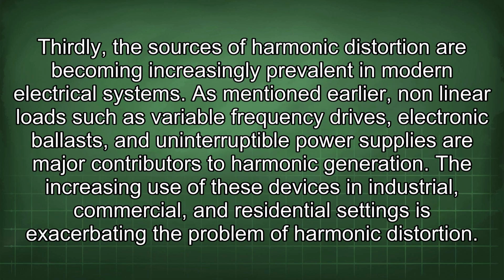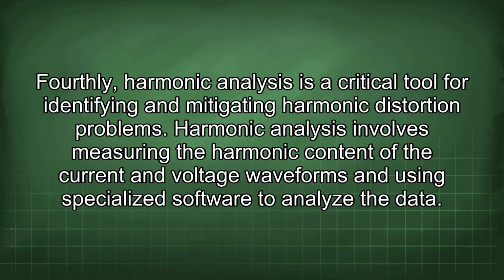Thirdly, the sources of harmonic distortion are becoming increasingly prevalent in modern electrical systems. As mentioned earlier, nonlinear loads such as variable frequency drives, electronic ballasts, and uninterruptible power supplies are major contributors to harmonic generation. The increasing use of these devices in industrial, commercial, and residential settings is exacerbating the problem of harmonic distortion. Fourthly, harmonic analysis is a critical tool for identifying and mitigating harmonic distortion problems.